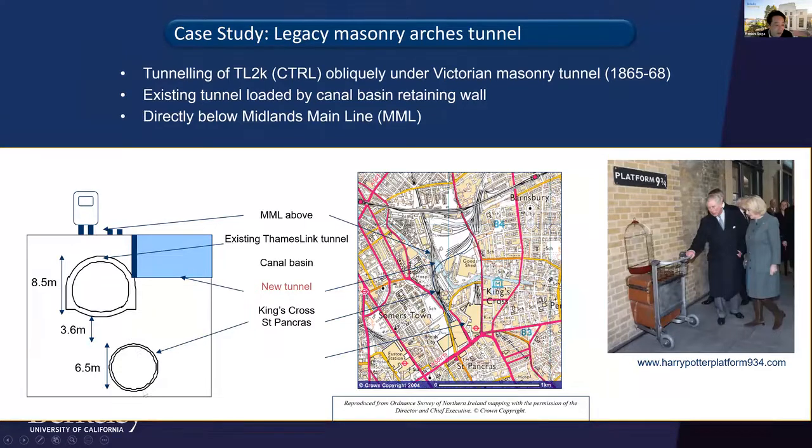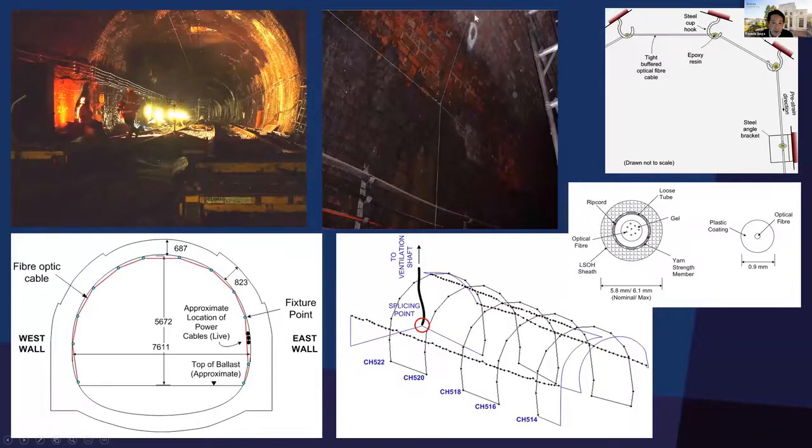So you can see when the excavation is done over here, this particular tunnel gets distorted. And then there's some sort of a disruption in terms of the other neighboring infrastructure. So we attached the optical fiber around the tunnel, like these 5 different cross sections, and then 3 longitudinal directions. But the point is that this becomes one line, and it goes to the interrogator to measure strain all over the places and give you the distributed strain along here.